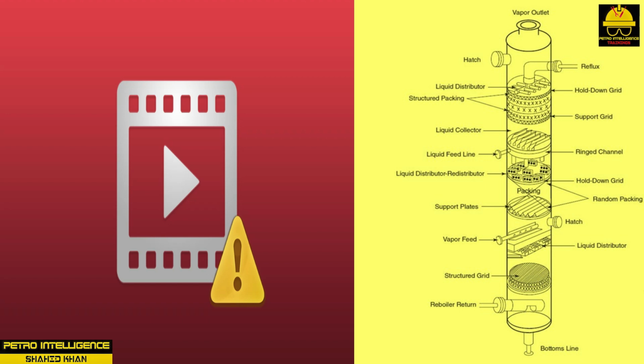There are 3 types of packed distillation columns: random, structured, and stacked. Random packing includes discrete pieces of packing that are randomly dumped or poured into a packed column. Packing provides a surface for good vapor-liquid contact, distillation efficiency characteristics, and predictable pressure drop. Structured packing has specific geometric shapes, like a mesh. It works best in columns requiring high liquid loadings. Stacked packing is uniformly arranged inside a distillation column. Packed columns are designed for pressure drops between 0.20 and 0.60 inch of water per foot of packing medium.